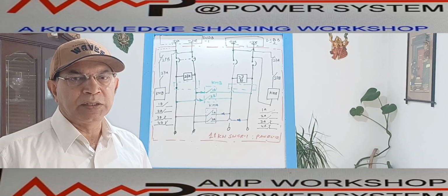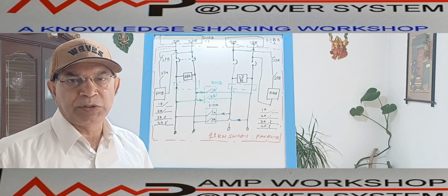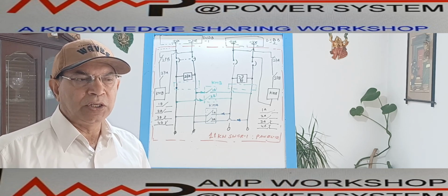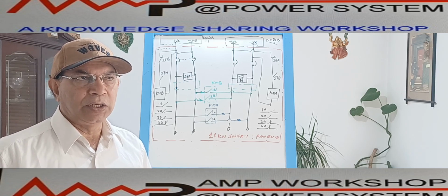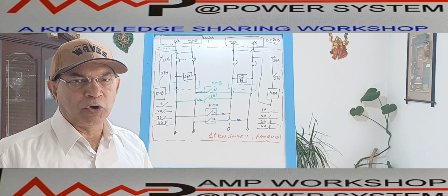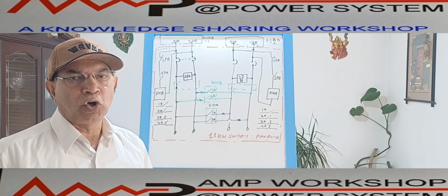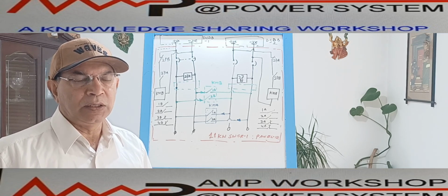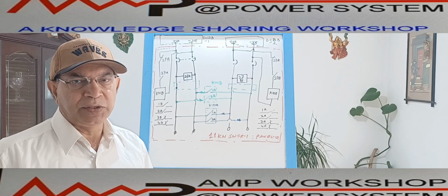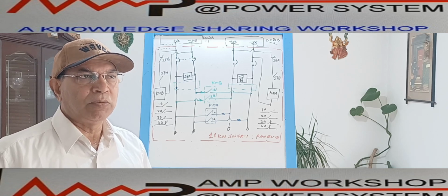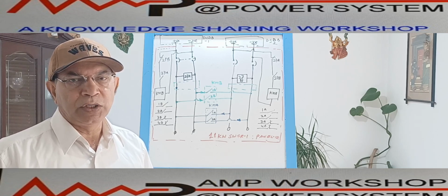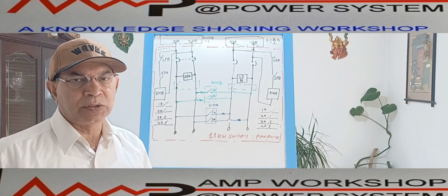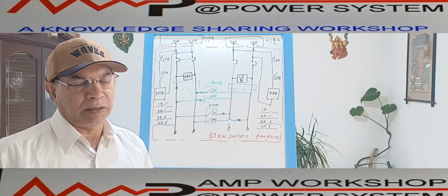Inside that panel, the necessary wiring or changeover process is made. Now, the intention of this changeover process is that in case of failure of any of the power supply, the supply should not be interrupted. So the various AC auxiliary power devices or the 120 volt DC or 48 volt DC control devices should get the power uninterrupted.